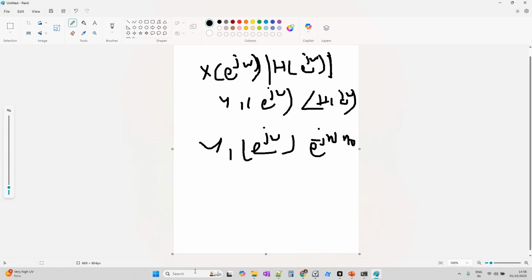So we know from the properties of the DTFT, this is nothing but, in the time domain, y1 of n minus n naught. So this is the output. What happens is, when the linear phase is there, the output waveform is preserved. If the output is triangular, then the waveform will be preserved, but only a delay will be there.